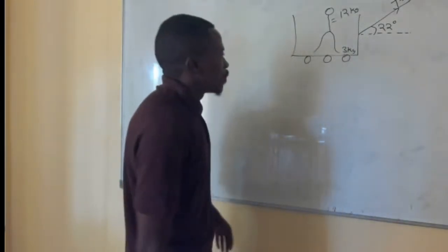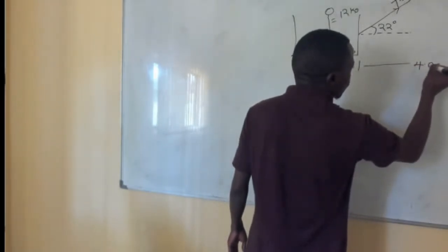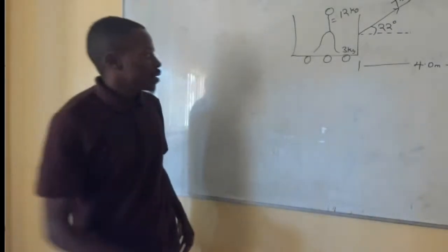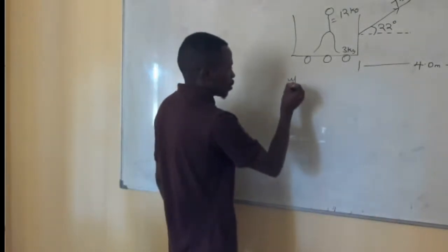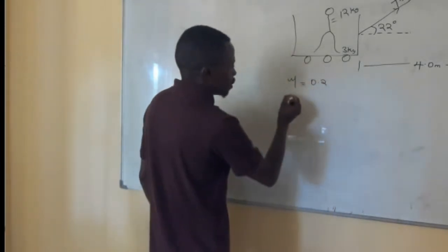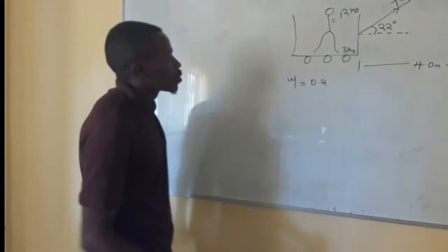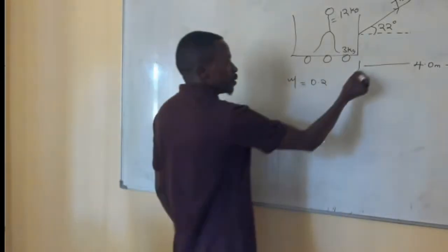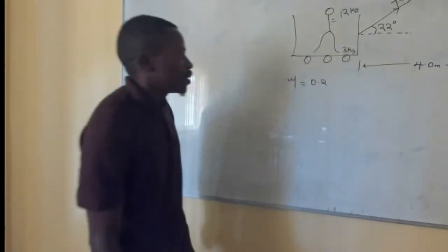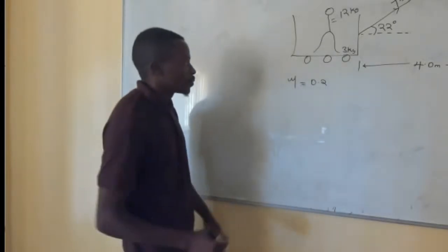We are being asked to find the speed after the wagon has moved some 4 meters across the living room. In this case, we've been given the coefficient of kinetic friction to be 0.2. We've also been told to specifically use the work energy theorem to come up with the speed that is required to move Leandro 4 meters across the room.